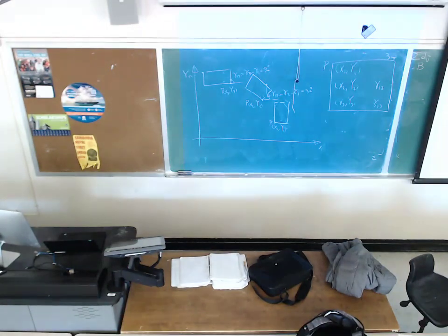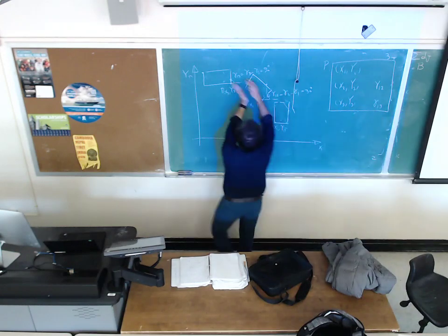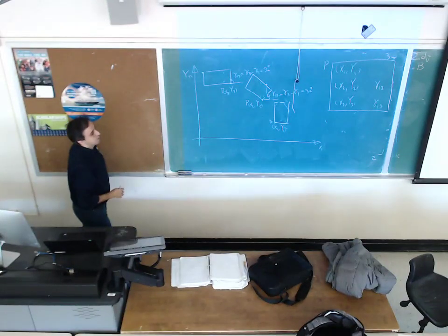The application for that, we have these conveyors here, conveyor 1, conveyor 2. So you would like to design a 4-bar mechanism such that it's going to take these parts from this conveyor at this orientation, and it's going to move it to this desired position at this orientation, and then it's going to move it to this third precision point at that orientation. So it's kind of moving this box through these 3 precision points.